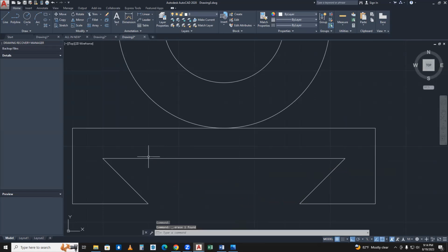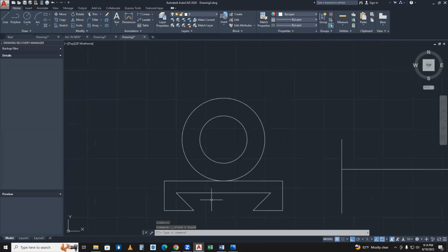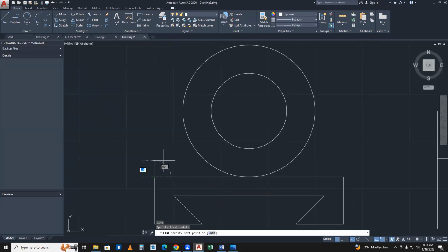So everybody's clear on the different ways we can do a drawing. Fine. So the easiness and the time saving, that is the reason we're using different shortcuts. If not, we can do it in a different way. Okay, now we have to draw this line, right? That one we'll learn later. So for now, we'll just connect these points, because the tangent point will be shown when you put the snap mode on. So I'm connecting the dots.